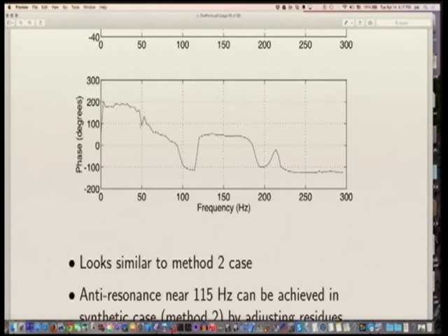But you do see that maybe we don't want to high pass at 50 hertz. Maybe you want to high pass a little bit higher. The lowest note of a guitar is around 80-something hertz. So let's go ahead and high pass down here, because if we do that, then we get a nice pretty phase curve varying in a nice range that's clearly within plus or minus 90.